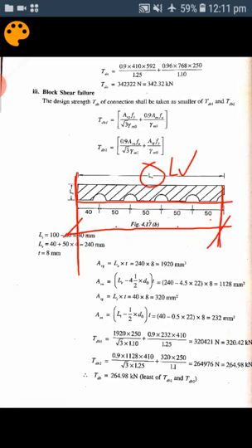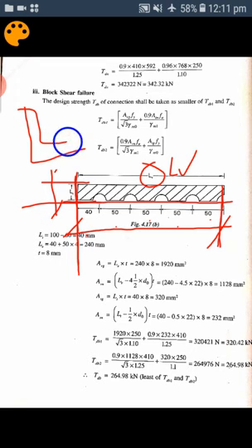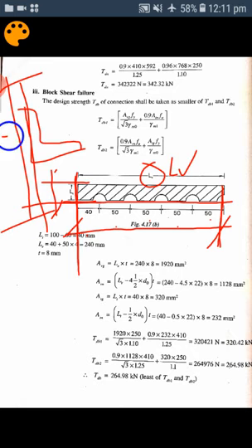So that is LV. Then LT is to be taken perpendicular to that, from the center of the bolt hole till the toe of the angle section. If this is the angle section connected to the gusset plate, and this is the bolt, you have to take from the toe to the center of the bolt hole as LT. I hope you understood this one.